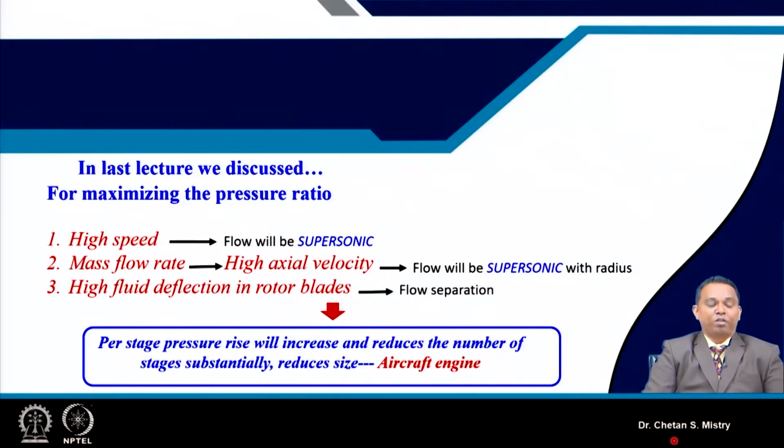The third option we have discussed is higher fluid deflection for the rotors, and that is what will lead to the flow separation issue. So discussing the first two options, the flow is going to be supersonic, and that is of major concern and interest for these lectures.